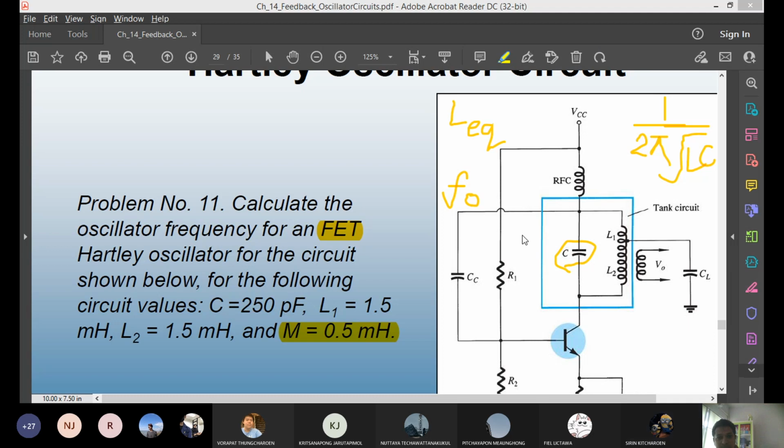Teacher, if we calculate right away using the formula, we don't need to inverse, right? No, you don't have to inverse. I just showed you a mathematical trick in the calculator. Sometimes when you do 1 over 2 pi, how many brackets do I have to put? Let's see. 1, 2, 3. What is your answer again? 159.15 kilohertz. Okay, I got the same thing now. Yes. Students miss the brackets, and then the answer that comes out is quite funny.